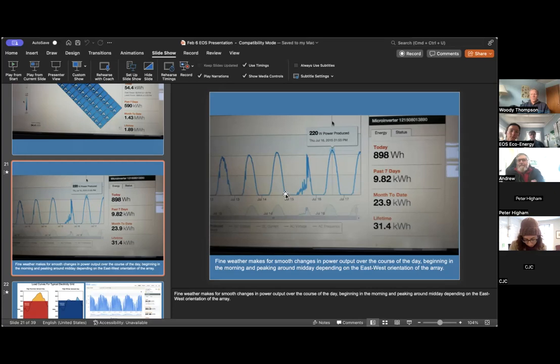In a typical home, the major energy consumers are heat pumps or your heating system. The hot water tank takes about 3,000 watts. The electric kitchen range oven takes about 4,500 watts, at least 3,000 watts, depending on the model. And then each burner is about 1,500 watts, and you've got 4 of them up there. So you're looking at about 6,000 watts for all the burners on top of the stove. So a typical home really consumes a lot of power if you just use everything and don't reduce your consumption.